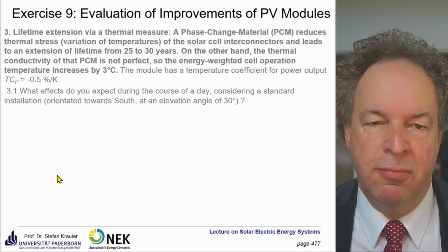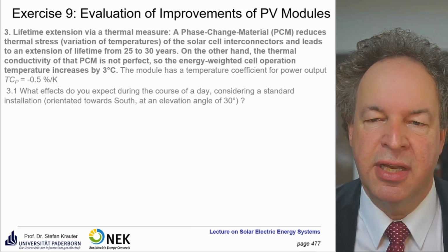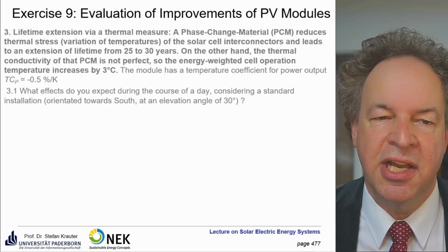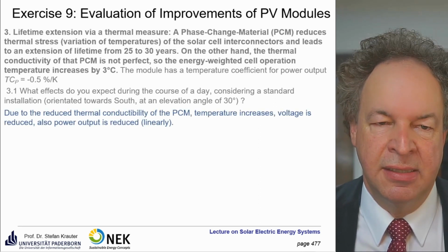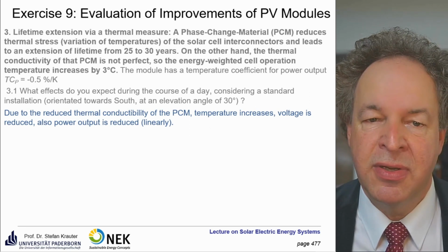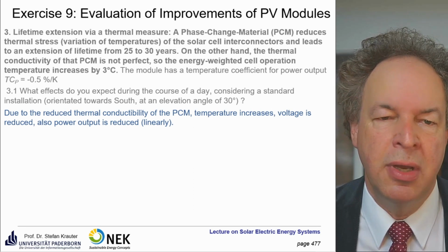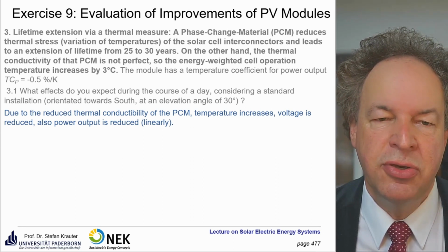First question is, what effects do you expect during the course of the day, also considering a standard installation? And yes, due to the reduced thermal conductivity, temperature increases, voltage is reduced, and also power is accordingly reduced linearly.